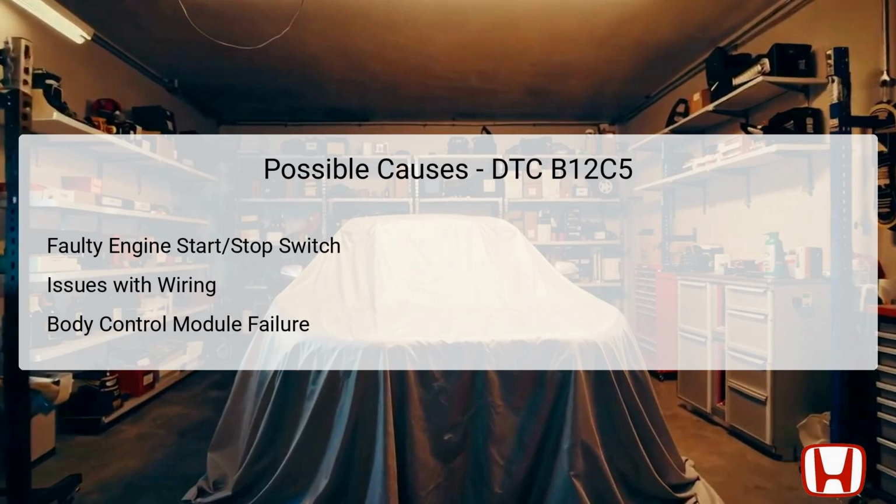Lastly, a failure in the body control module itself can result in an inability to communicate with the engine start-stop switch, thus triggering the error code. Each of these causes needs to be systematically investigated during troubleshooting.